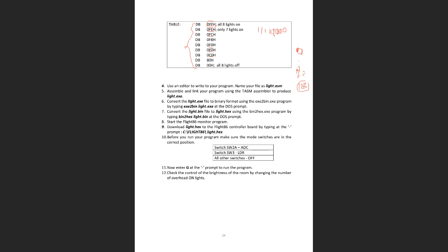So what will happen if we divide it by 16? 128 divided by 16, it becomes 8 values, right? So that's why actually we divide this analog value by 16, we will get 8 different values, and these 8 different values, because we have 8 different values of LEDs, we have to adjust it. You get my point? Is it clear why actually we divided by 16? Is it okay?